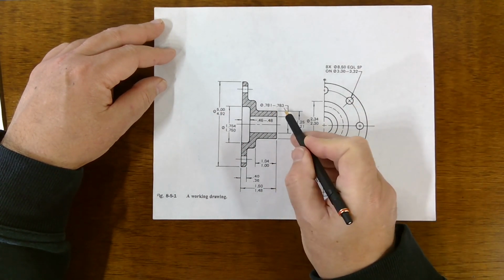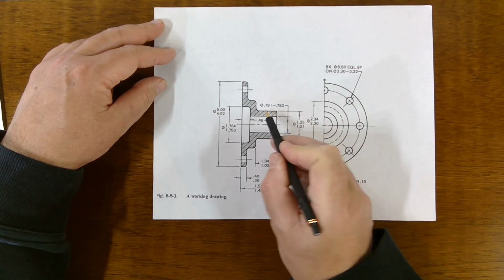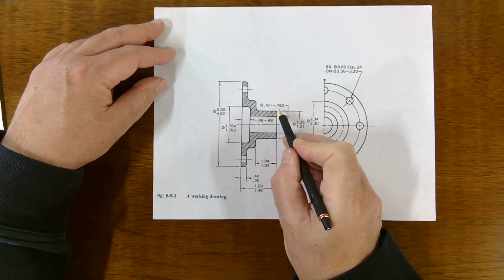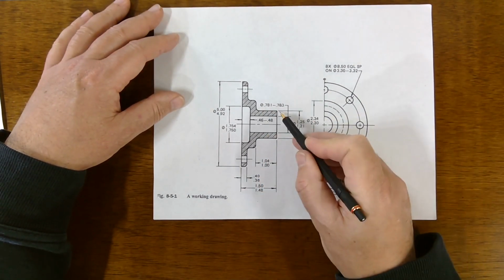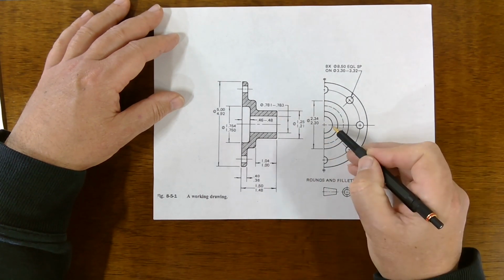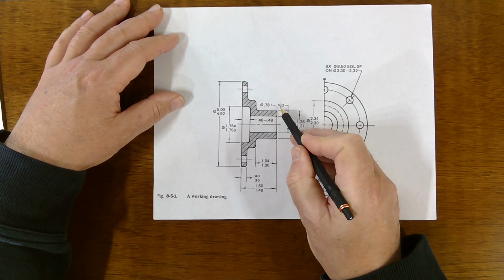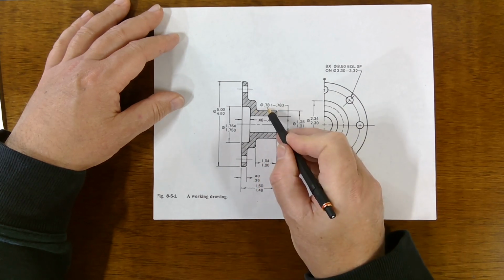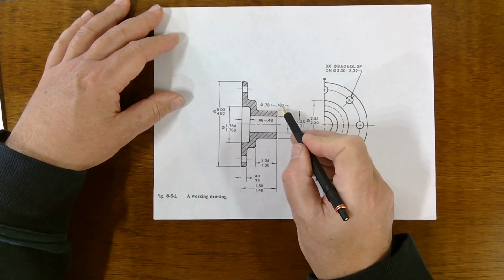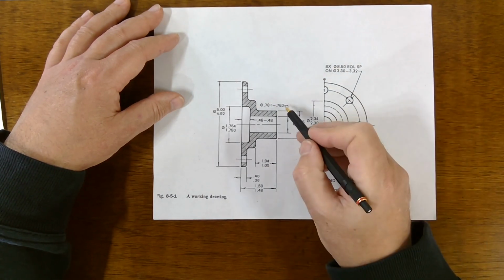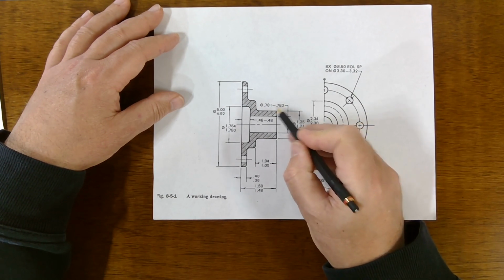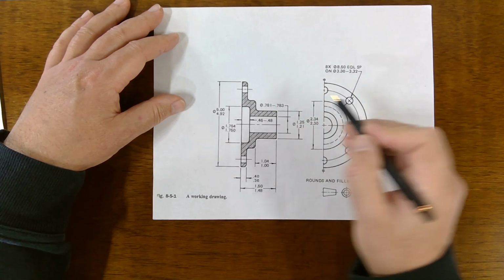Okay, here is another way to specify a tolerance, and it looks like subtraction, but it's really just the biggest allowable value and the smallest allowable value. And once again, this symbol here means diameter. So they're saying that this distance here, which is this circle, right, has a diameter of at least 0.781 and no bigger than 0.783. So you can make this hole any size between these two, and that's okay, right? So the tolerance is the difference between these two. It would be 0.002, right? Because this number minus this number, the difference is 0.002.